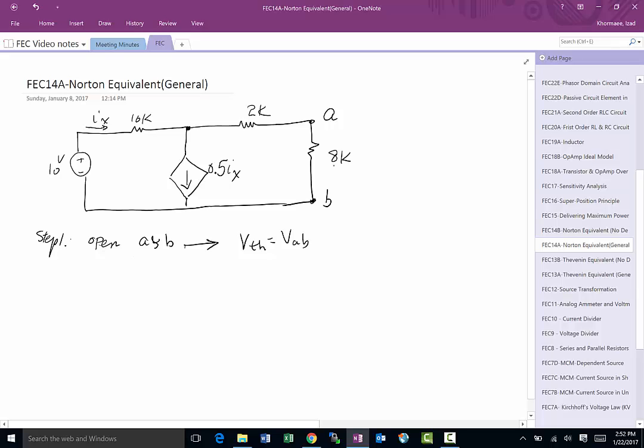Now, when we say nothing, we're not talking about cutting the elements that are part of the circuit. We're talking about not adding load from external when we're doing the Thevenin equivalent, because this equivalent is supposed to be for the circuit excluding load and external stuff. Okay, so in order to do that, all we have to do is basically take the circuit and solve it either with KCL, KVL, or one of the other analysis tools that we have learned so far.